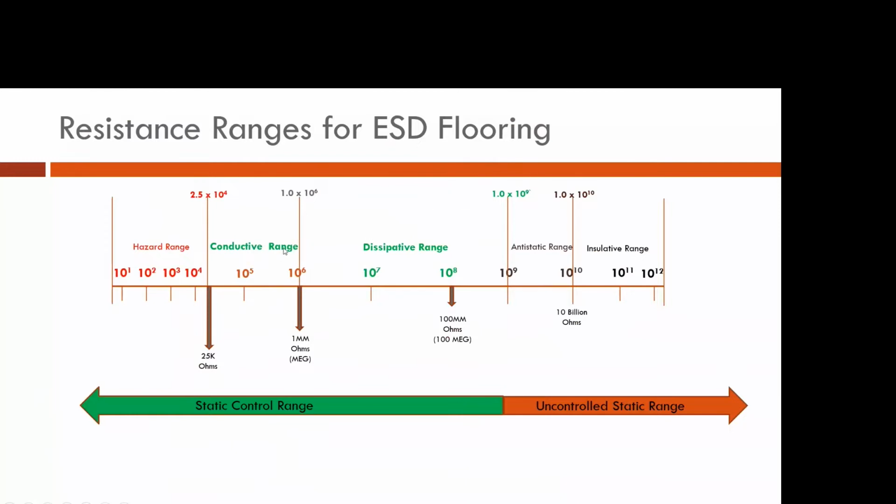That range is going to be covering both conductive and dissipative. Now, there is some talk out there about there being a sweet spot, that if you're within this range you're going to be safe and okay, since the ANSI standard doesn't tell you exactly what you're supposed to do, so being in the sweet spot will cover you. And that's a misnomer. It's like saying that you don't need to be connected to the ESD floor via heel grounders or ESD shoes to have the floor function and work properly with the human operator.